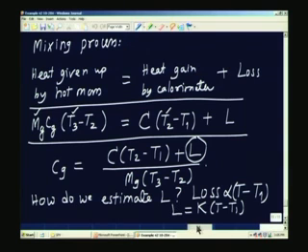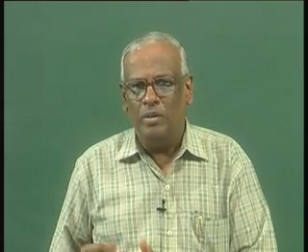So, we were looking at the mixing process. During the first phase, we are going to drop the hot mass into the calorimeter vessel, and then we are going to study the temperature variation of the calorimeter. The temperature actually increases steadily, and after some time it has to come to a steady state, and if there are no losses, the steady state temperature should be a constant value higher than the initial value of the temperature. Of course, because of the losses inherent in the system, this is not going to take place. Actually, the temperature will start coming down after increasing to a maximum value,